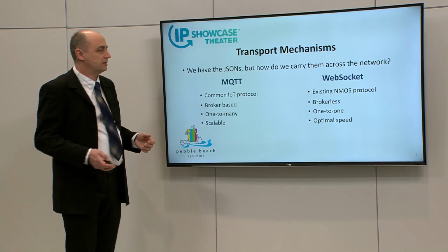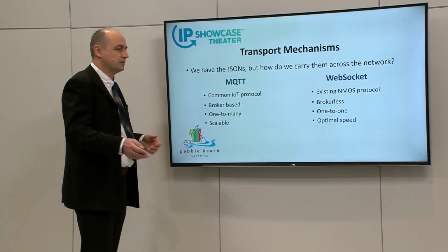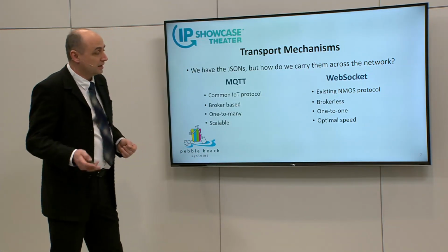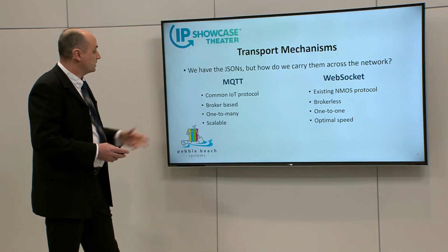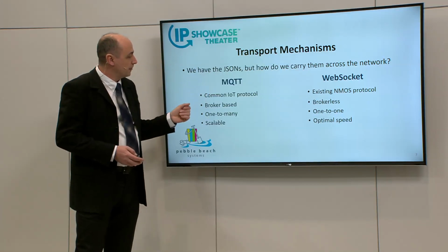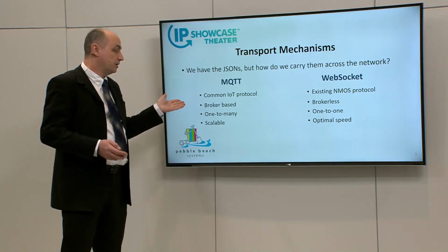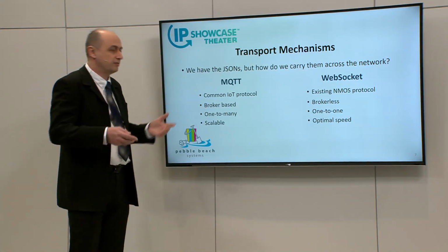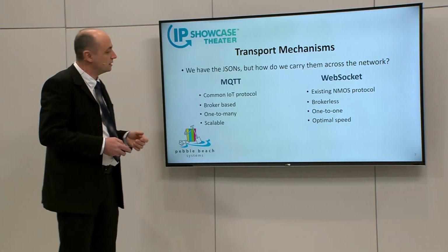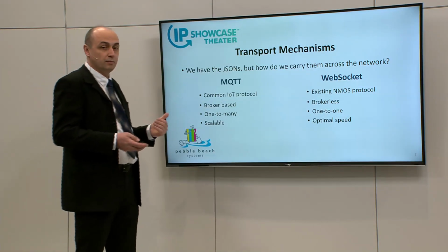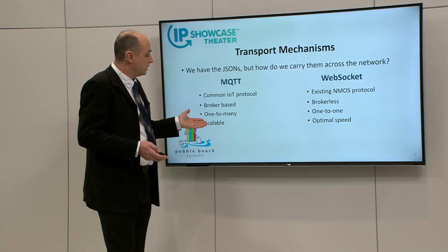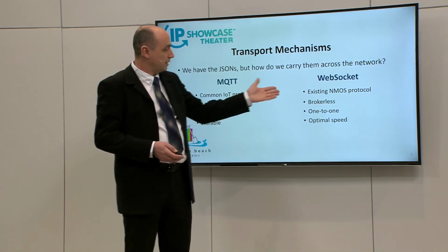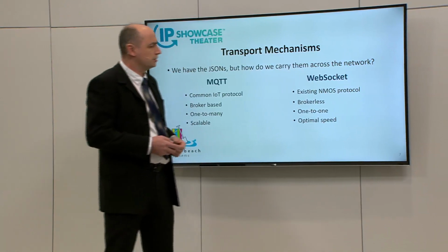So if you want to connect 5 machines, you would have 5 WebSockets listening to the source machine. But it covers a different set of use cases. For example, if you have MQTT, you have to administer probably a redundant broker. So you have to install it, administer it. You would have to have probably a couple of VMs that would be running that. So that is a little added layer of complexity, which is well worth it if you are talking about a big facility. But in a smaller system, it could be a bit of a burden to administer.